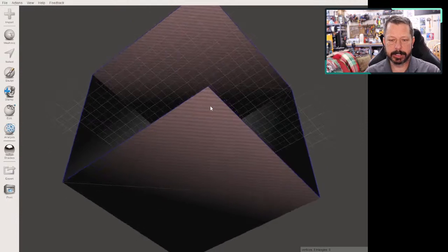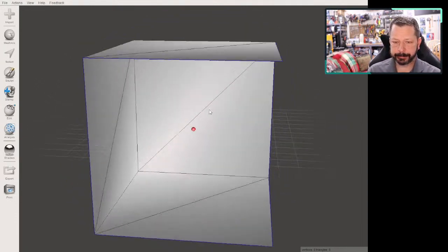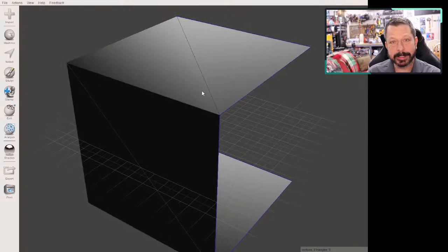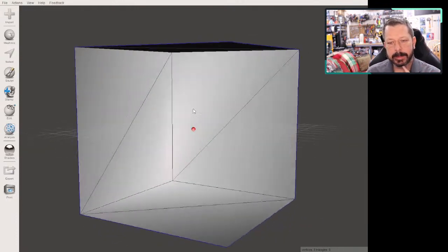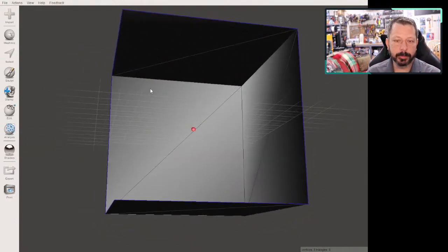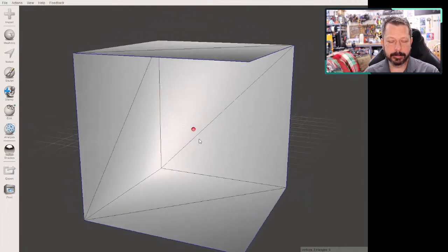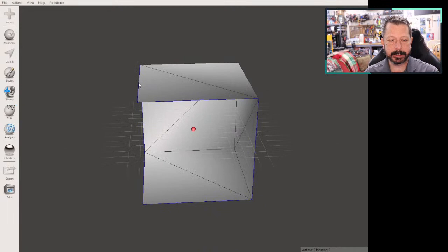There it is. So these faces here only have a plane, no thickness, and the thickness would have to come by adding more faces, right, to make some kind of a little edge and an inside surface and all that. So this would be non-manifold, and it wouldn't print because it doesn't actually enclose any volume that the slicer can make sense of.